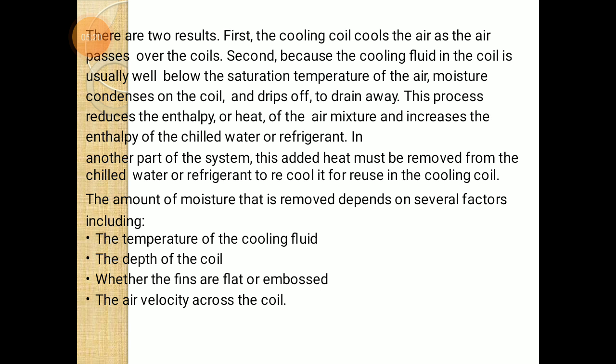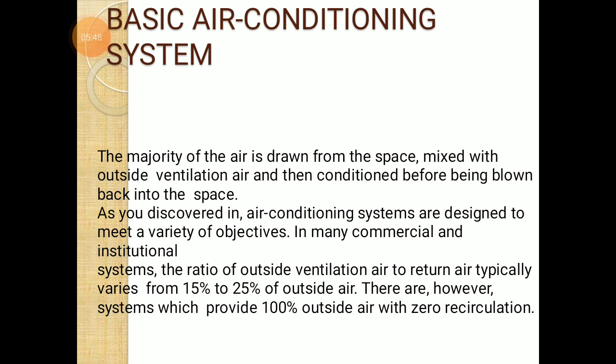In another part of the system, this added heat must be removed from the chilled water or from the refrigerant to be cooled for reuse in the cooling coil. The amount of moisture that is removed depends on several factors, and that includes the temperature of the cooling fluid, the depth of the coil, whether the fins are flat or embossed, the air velocity across the coil, etc.